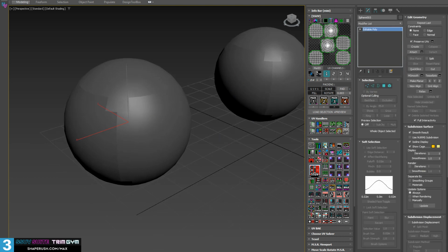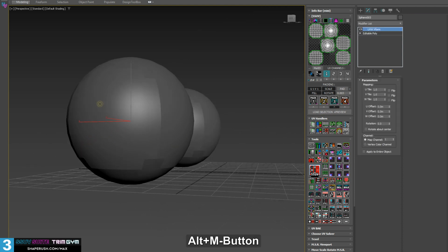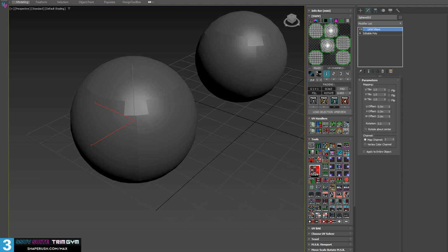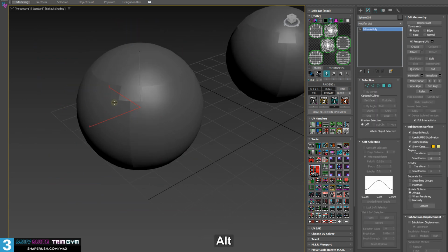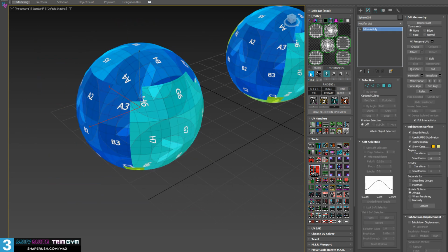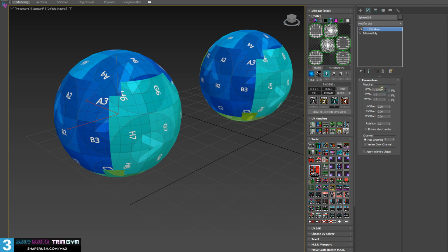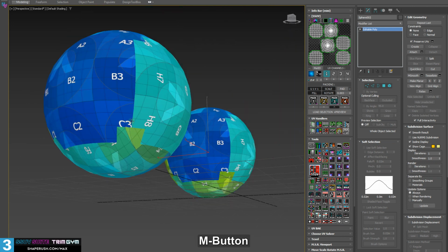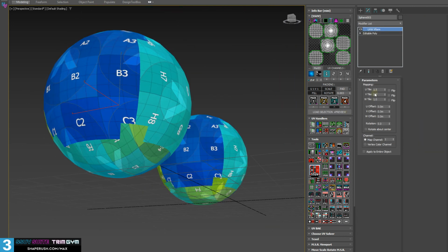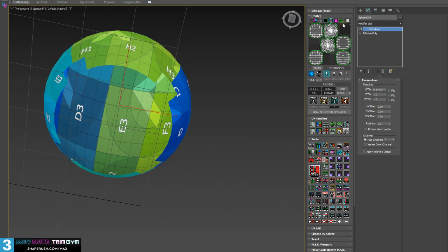Next, we have UVWX form with the left click. Okay, and you can't see that in the viewport. We'll change that in a moment. And with the right click, we get the X form modifier added. I'm going to collapse this back down and turn on the checker override. Now that we are in here, we're going to add the UVWX form once again and change it. You can see that. Okay, we're going to get there sooner or later. There we go. You can see that we can change the information here, and that's based upon what we have